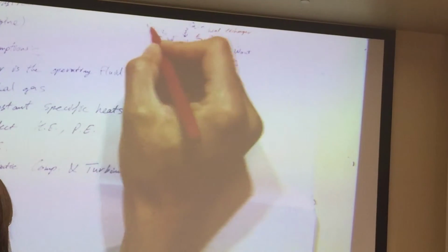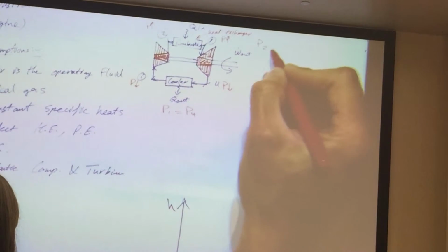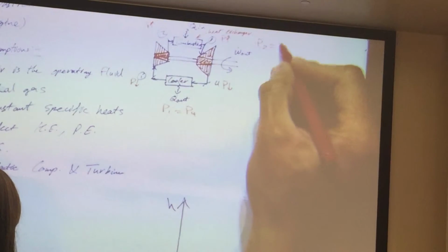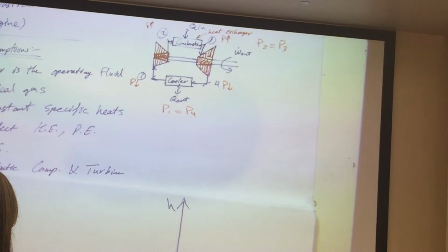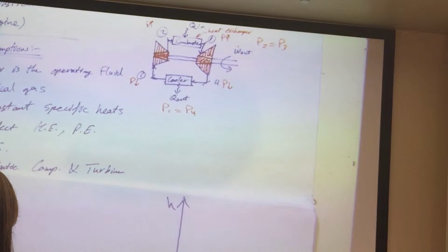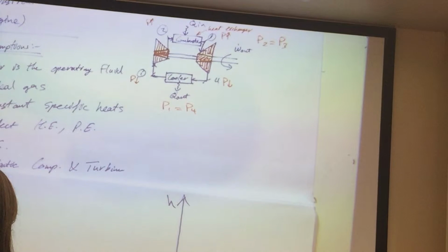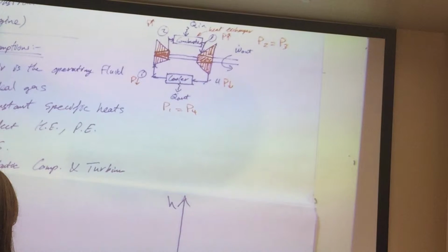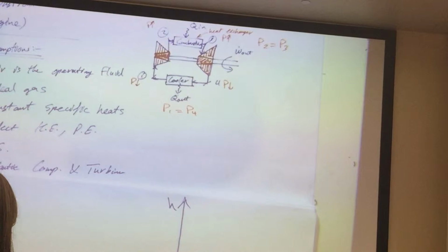So meaning that P here is high, P here is high, and they're both equal. So P2 is equal to P3. Now, does that make sense? Yes. If I go from a low pressure and I compress it through my compressor, and I'm burning, transferring heat and expanding my gas, then passing it through a turbine, which essentially took heat input, some form of energy, transferred it into flow work, the gas expanded, went through the turbine, and produced what? Work. So that's the same principle.